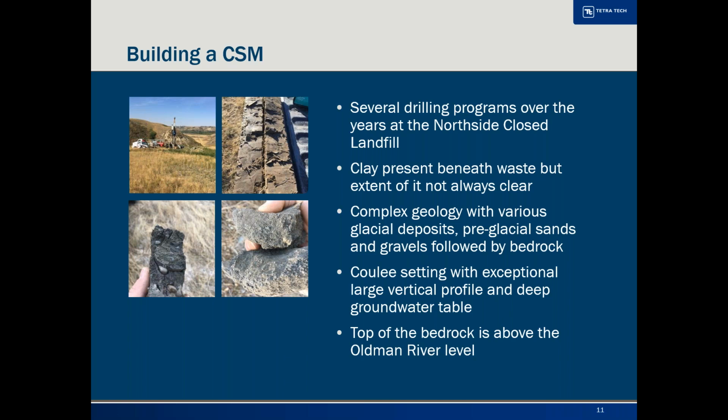We have identified that there is actually clay underneath the waste, and these are a couple of tubes that we took from the waste, and it's from underneath the waste, and it's definitely a nice, fairly plastic clay where we took this sample. But the geology is complex, and this goes for the entire part of Lethbridge, where you have fairly excessive thickness of glacial tills, various sequences.